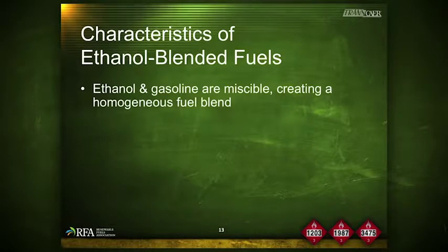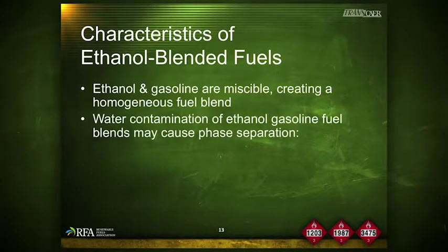Blending ethanol with gasoline has multiple effects. The higher the concentration of ethanol, the more the fuel has polar solvent type characteristics, with corresponding effects on conducting fire suppression operations. Water introduction to ethanol and gasoline fuel blends has a dramatic effect. Without water, ethanol and gasoline blends are homogeneous. Ethanol has an affinity for water. For instance, it is not necessary to add any gas line antifreeze to a gasoline ethanol blend, since the ethanol will absorb trace amounts of water and pull it through the fuel system of the vehicle.